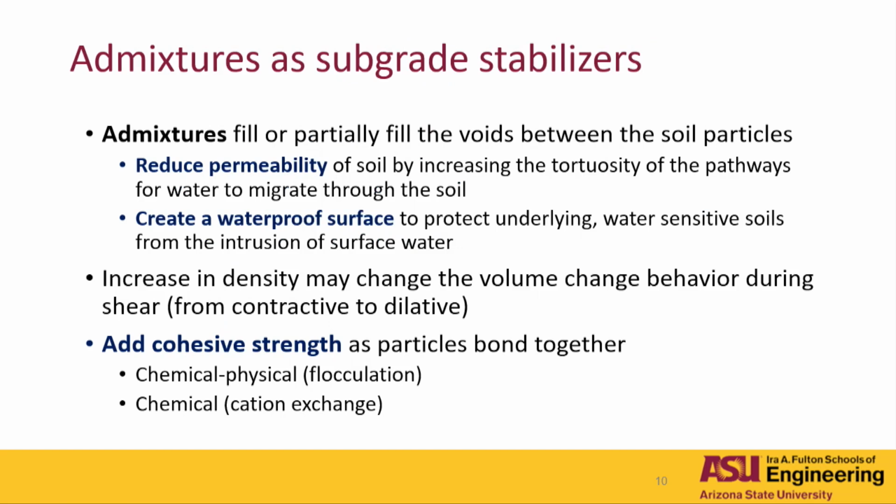It also increases the density of the material, right? And now for shearing behavior, instead of getting a contractive response because you have a looser material, now you get a more dilative behavior.